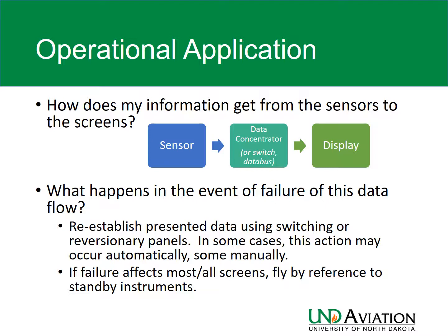If all or most screens are affected by a data flow failure, you have to fly by reference to standby instruments and then work through the problem with your crew member using good CRM and, of course, your company handbooks and manuals.